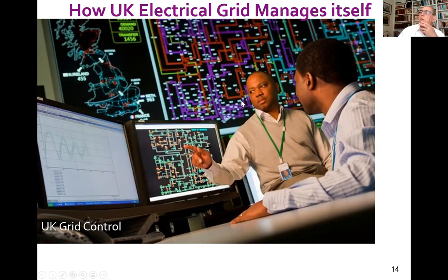Now, what's going on between the shift charge engineer and this gentleman, this guy, he's looking after this part of Britain. And he's got a frequency issue. And he's talking to his boss, what do I need to do? And the guy's telling him, you need to increase generation at this power station and that power station, and you need to talk to France, EDF, and see if they can raise their generation so that you can solve this problem. So this is how we manage the grid.